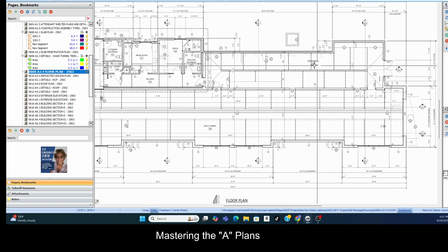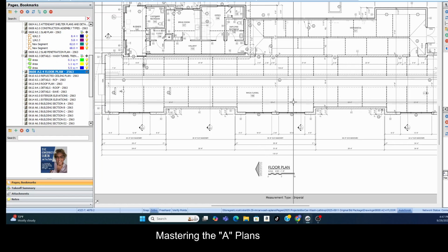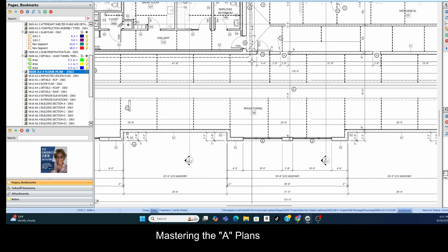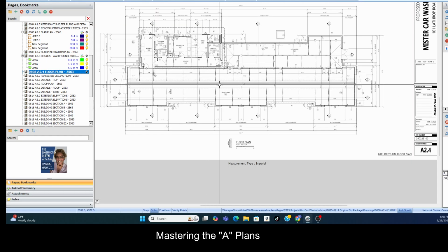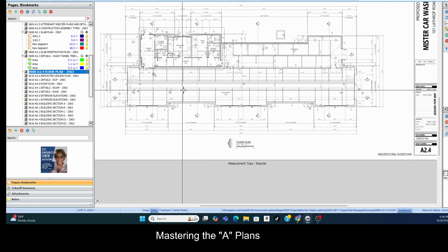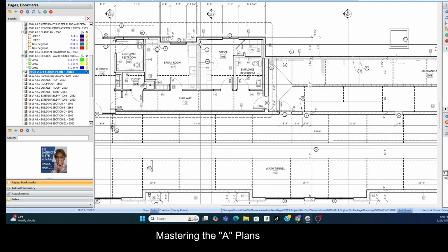That's why it's really important if you're a demo contractor that you understand how to read all of the plans, because you need to make sure you're not about to knock down a structural wall. They're not going to tell you. You have to tell them. So yeah, if it's built on a continuous footer, then it's a structural wall, right?